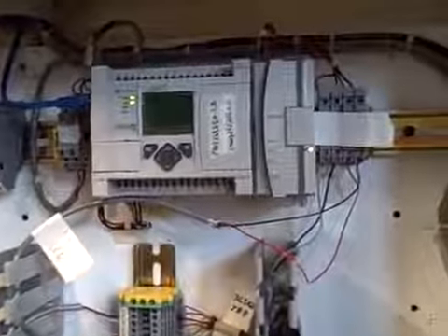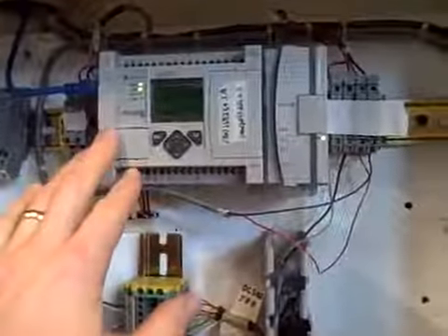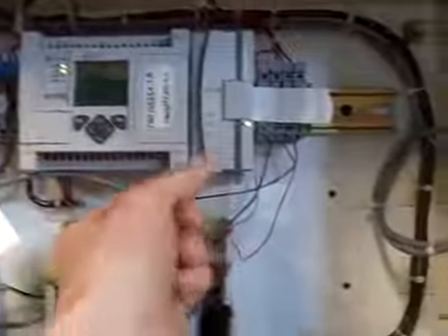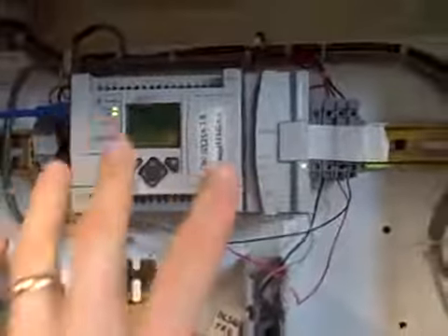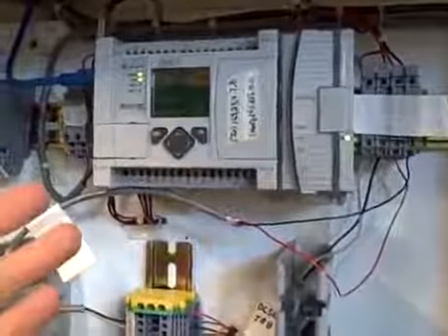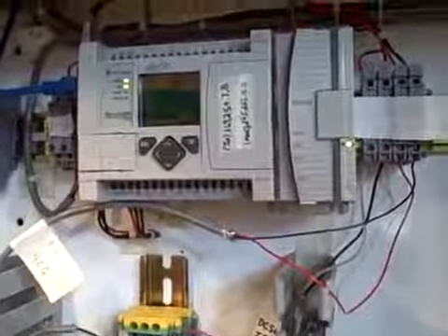In the instrumentation lab, we have a number of Allen Bradley MicroLogix 1100 PLCs equipped with analog input-output channels, enabling them to become full-fledged loop controllers, PID loop controllers. Right now, a team is using this PLC to control an air pressure process over here. I wanted to describe briefly how we access these controllers through the remote network and how we're able to change some of the important parameters inside to use them as a loop controller in your process.